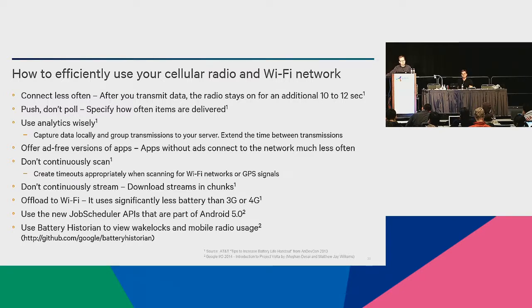One is connect less often. After you transmit data, the radio is going to stay on 10 to 12 seconds, so be aware of how often you transmit. Push, don't pull. Specify how many items are delivered. If you're going to use analytics, be aware that there are big differences in performance, the amount of data they use and the amount they transmit, so be aware of that. Use them wisely.